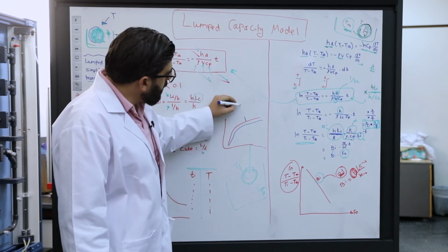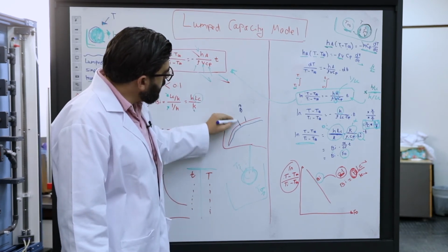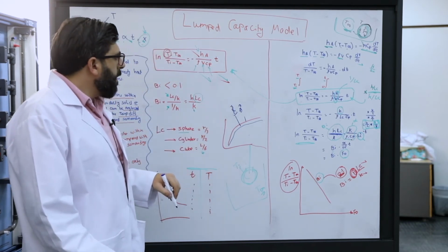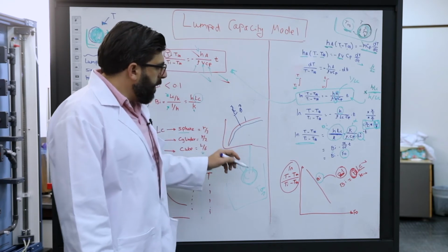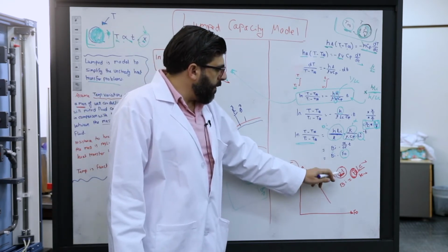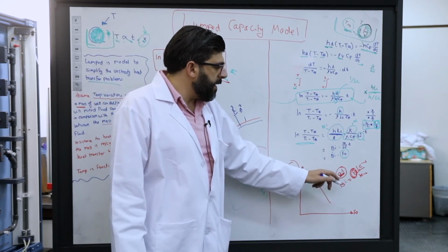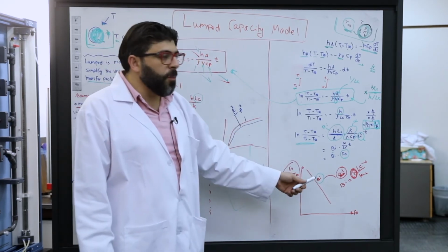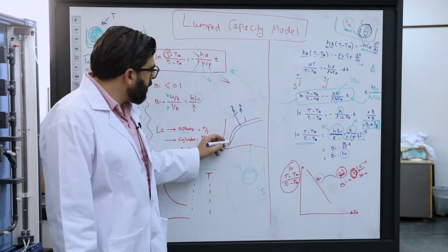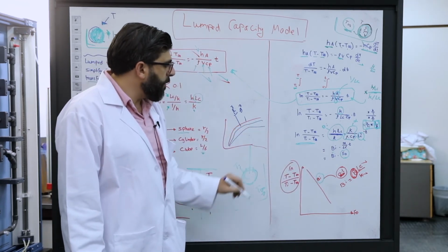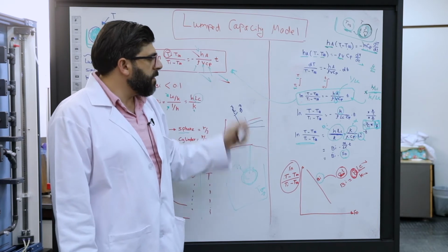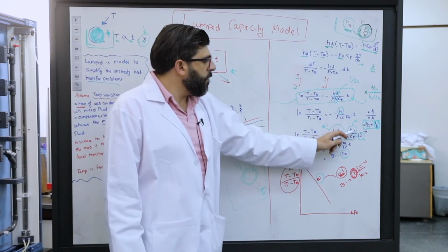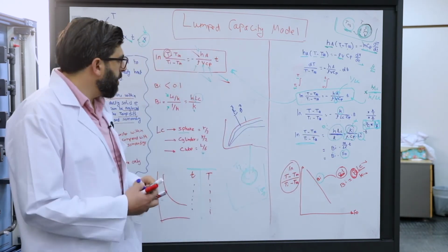So this is the experimental data, and this is the model. When the Biot number is 0.1 or less, the two curves will be very close to each other. If the Biot number is larger, you will find a difference between them, because there's no longer a lumped model. The internal conduction has a significant effect, so there's a resistance inside.